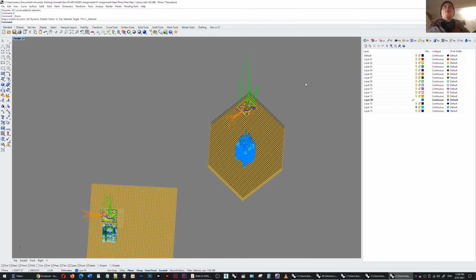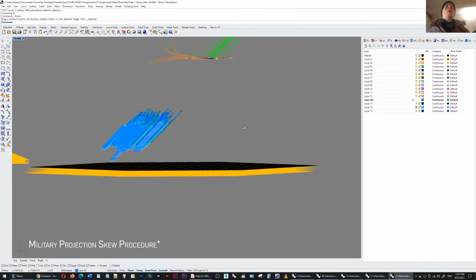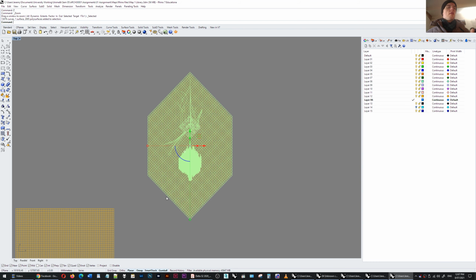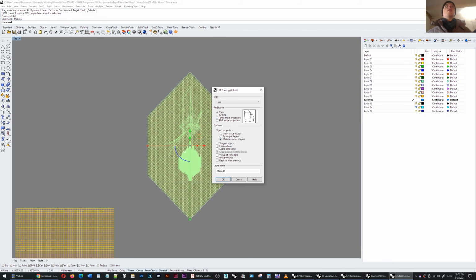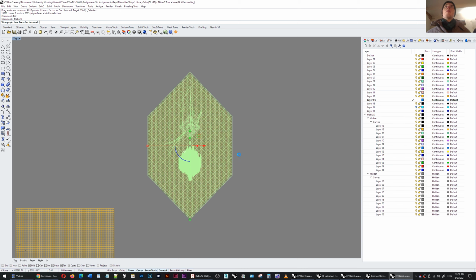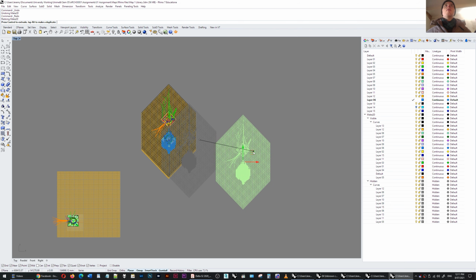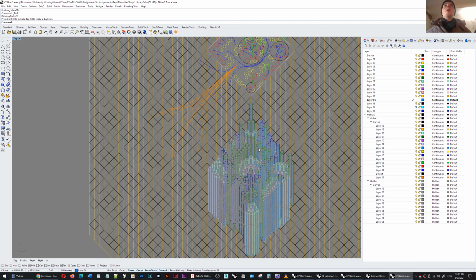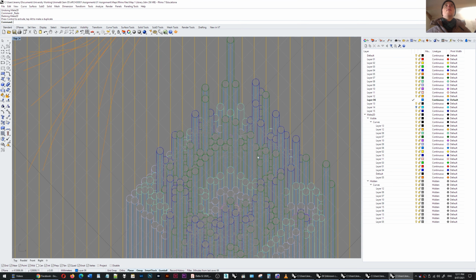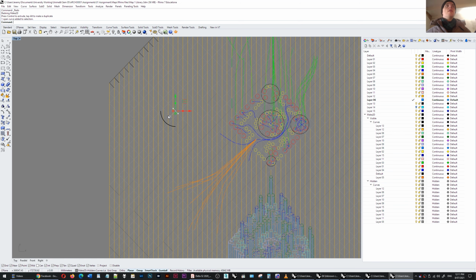So over here, I did the axonometric skew. So I'll do the Make 2D now, and I'll include the hidden lines. Now I've created the Make 2D. I'm going to clean it up a little bit before I export it to Illustrator. The first thing I'm going to do is remove the lines which I don't want to keep. Here I've got some doubling up, so I'm going to take those lines, find the layer,